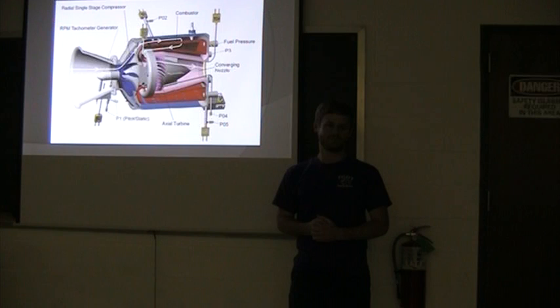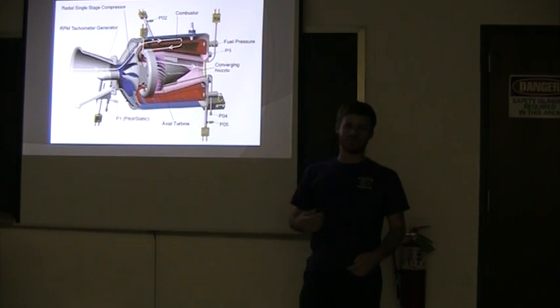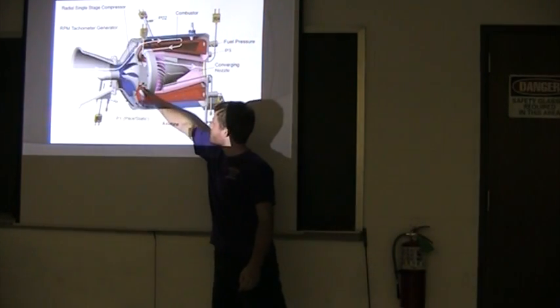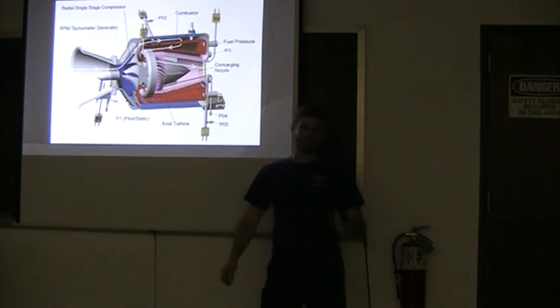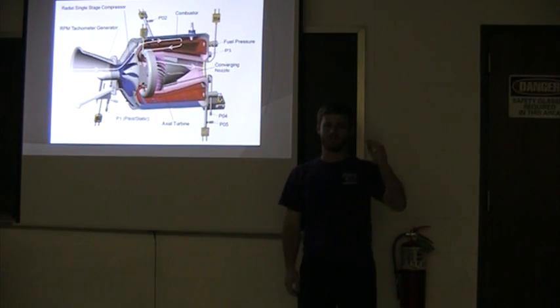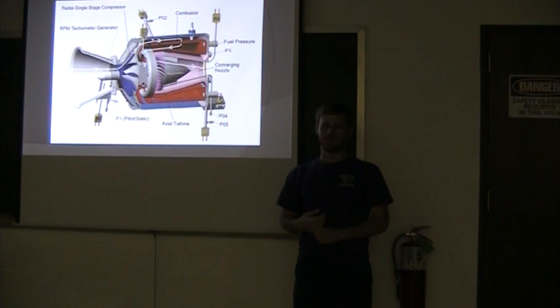So what can you do to increase the turbine efficiency? I mean, not the turbine, the efficiency of these? You increase the air temperature and pressure coming through the turbine, right before it gets to the turbine. You want really high temperature and pressure. But you don't want to do too much because you can run into material problems, or even if you put really good materials, it can get a really high cost.